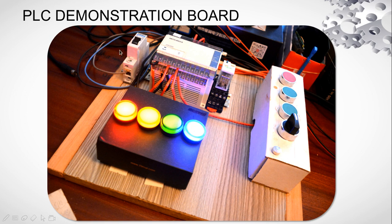So here we have our power, this incoming power. This is a safety device, and you have the PLC, the Mitsubishi PLC, here. We also have our inputs to the far right: the 3 push buttons and 1 selector switch, and all that is connected to the PLC to produce our outputs. Our outputs are quite simple. As a matter of fact, it's just pilot lamps. We have a red, yellow, green, and blue. So we are going to use the inputs through the PLC.